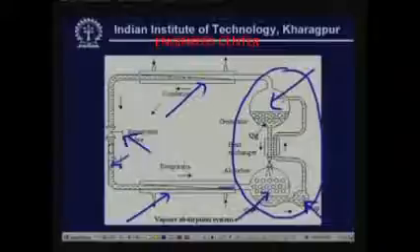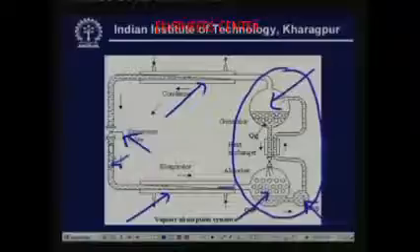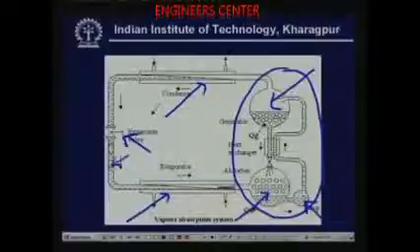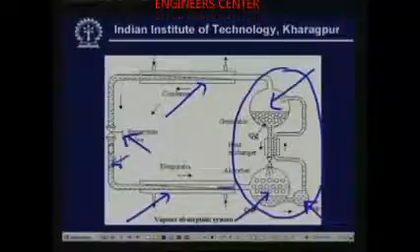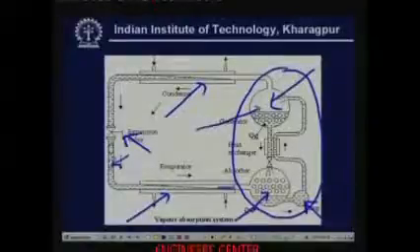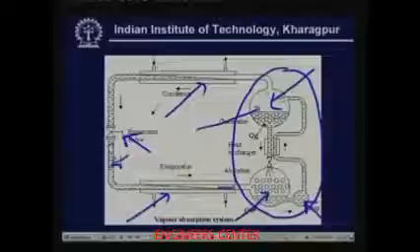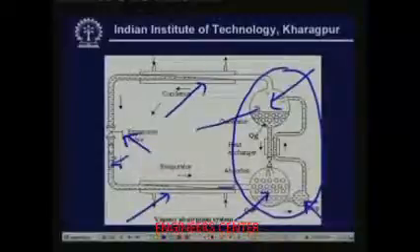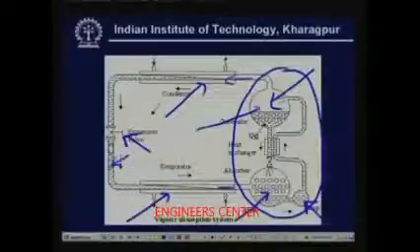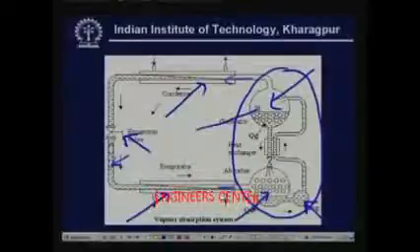So what we have to do is make it weak again. So how do we make it weak? Using a solution pump here, we compress this strong solution, that means strong in refrigerant, to high pressure, and then we pass it on to a component called the generator. In the generator, you supply high temperature heat to the solution strong in refrigerant. When you supply heat to the solution, refrigerant and absorbent get separated. The refrigerant vapor flows to the condenser, and since it is at a high pressure, it condenses in the condenser and forms a high pressure liquid which flows through the expansion valve, and the cycle is completed in this way.